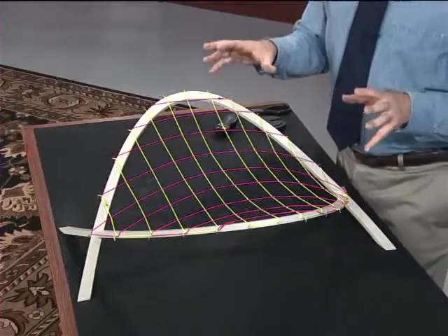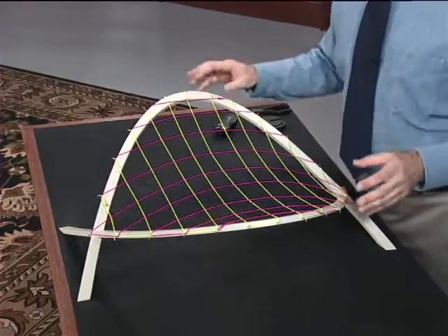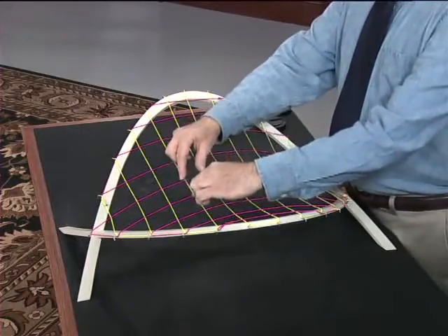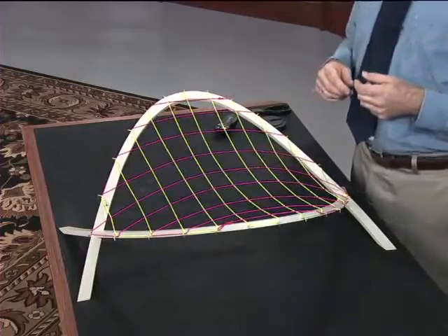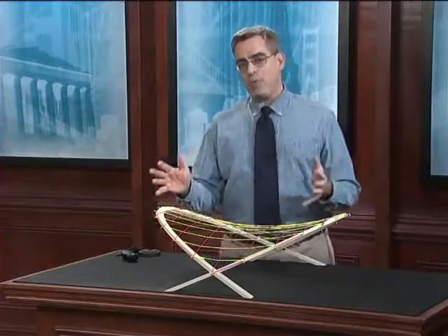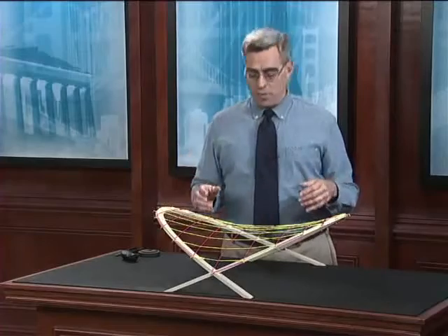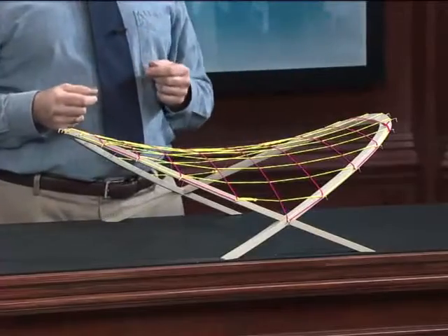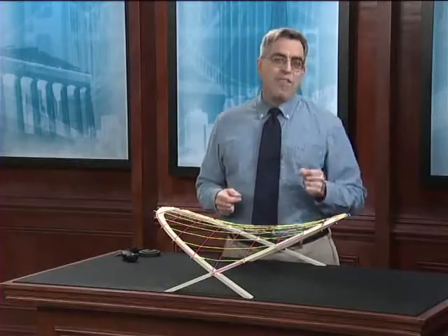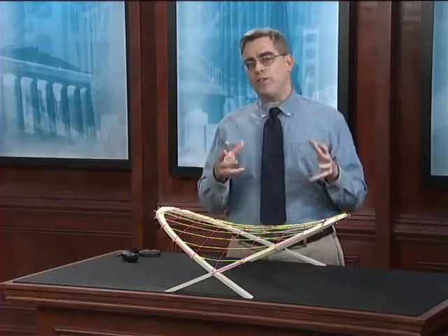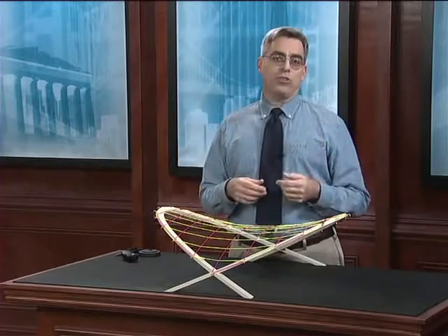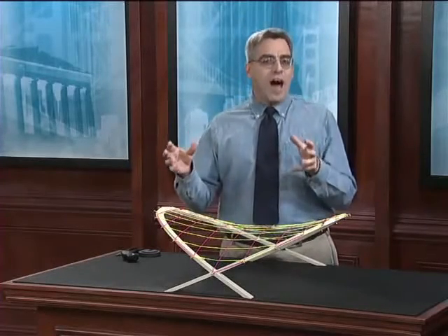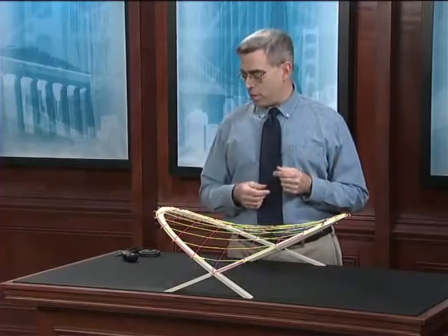In order to actually complete the roof of the real structure, once the steel cables were in place, a lightweight cladding of steel sheeting was added over the top with a steel panel located over each one of these rectangular grids. The result of the network of cables moving in both directions is a saddle shape. In fact, it looks very much like a high-par thin shell roof, as we covered a couple of lectures ago. However, this is not a thin shell structure. It's not a thin shell because it's acting principally in tension rather than in compression, and the roof itself is not a continuum in the way a thin shell concrete structure is a continuum made of monolithic concrete.